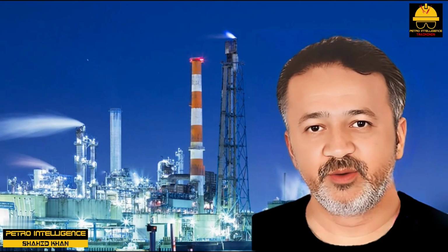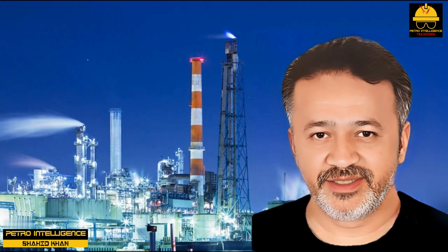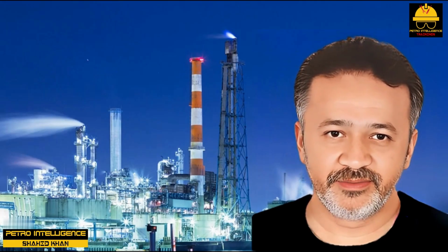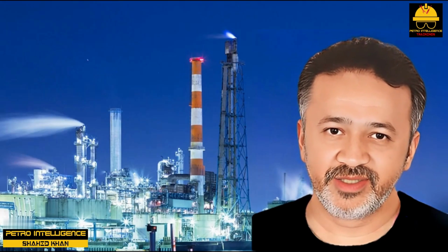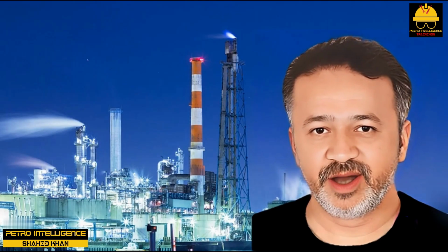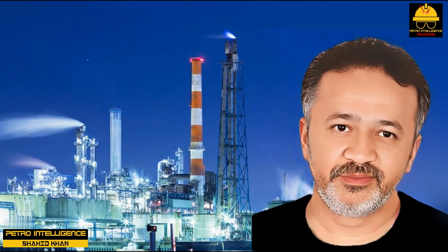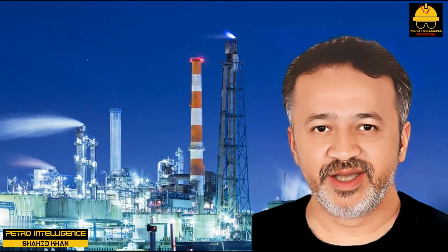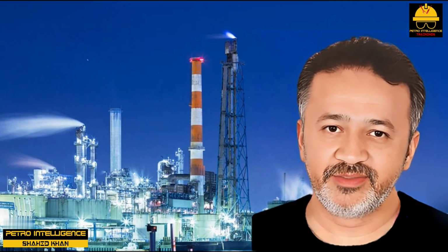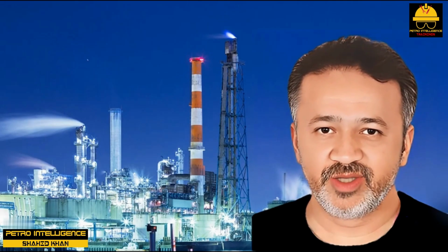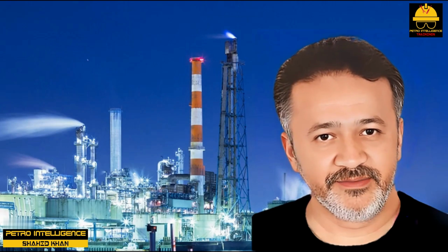Oxygen can be drawn into the refrigerant loop due to minor air leaks in the suction piping. To avoid this potential hazard, one should always maintain a positive pressure at the suction of any refrigeration compressor. To overcome this limitation, he increased the propane content of his circulating isobutane refrigerant from 5 to 10%.